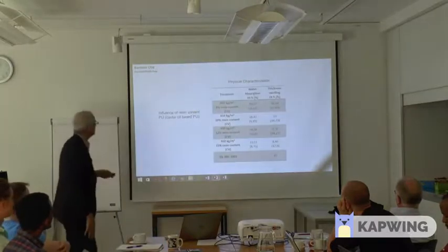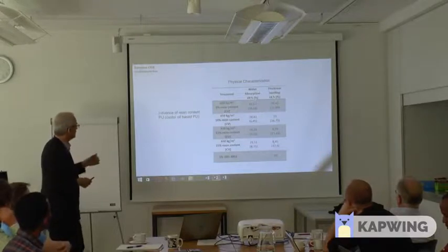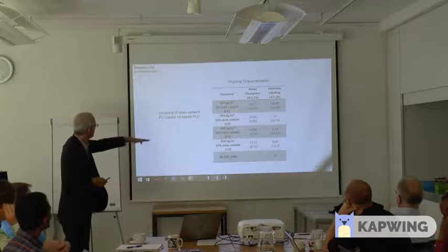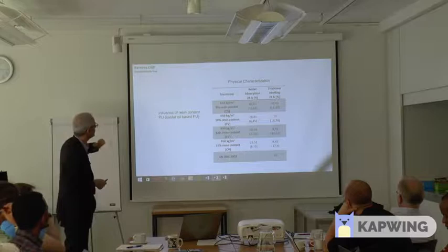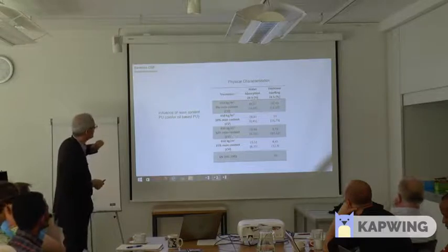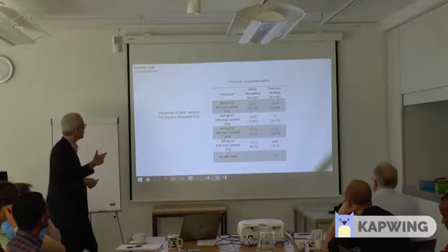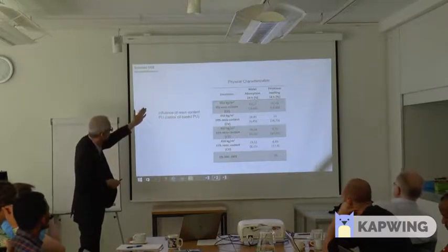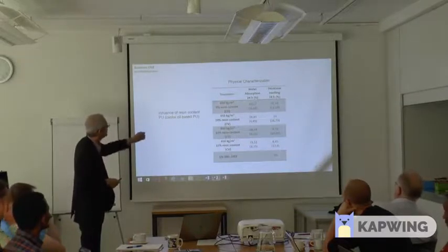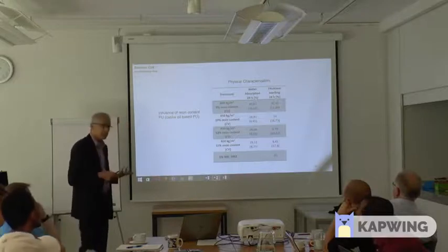The results were quite optimistic, promising, because comparing with European standards for that, 650 kilograms per cubic meter of density and different amounts of resin from 8 to 15%, we can follow how the water absorption and thickness swelling are, of course, reducing drastically with higher content of resin.